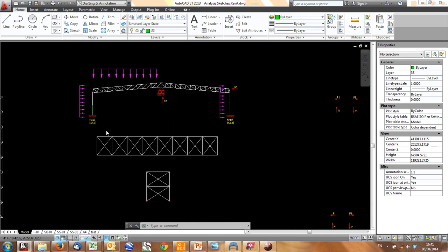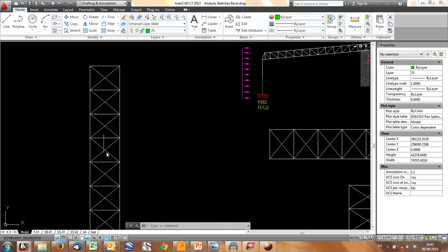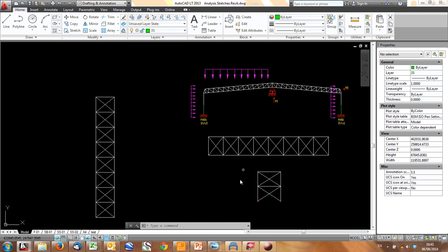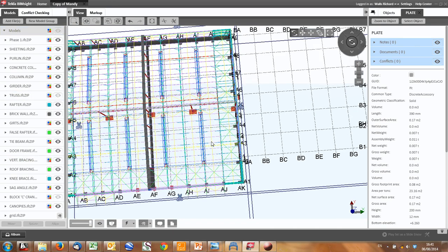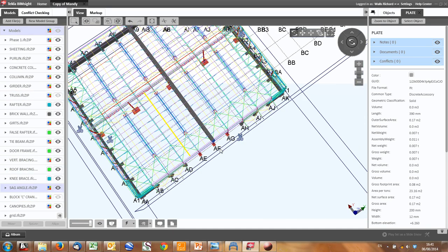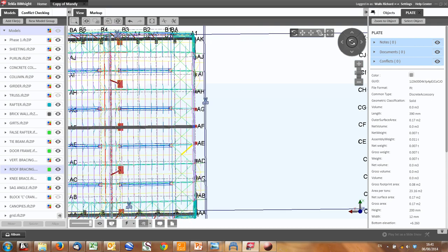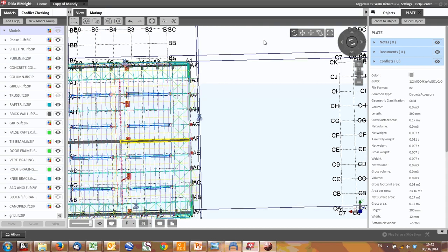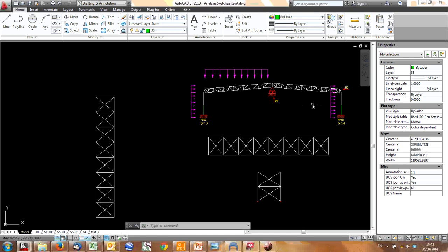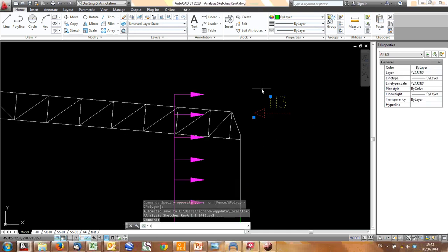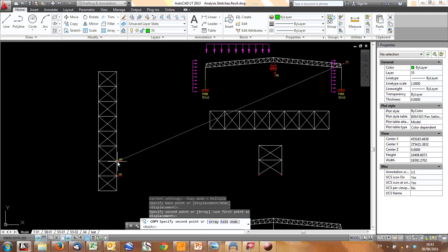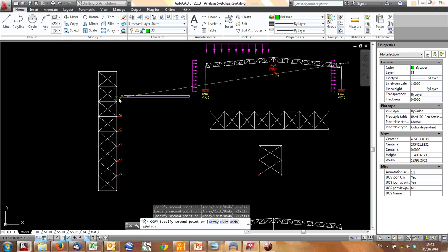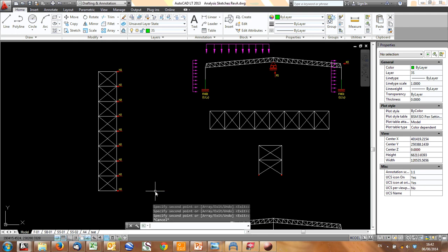Or we can draw it around either way. Let's have a look at it this way. So let's say this truss now supports that. So we're going to orientate it like this. I'm just going to try to do everything in the same direction, just to not confuse you, hopefully. So there's the roof bracing coming along. I get my horizontal load here, and now I can apply this to here. And that is how you take load from one part of the structure to another, all the way along. Once again, how is this supported?